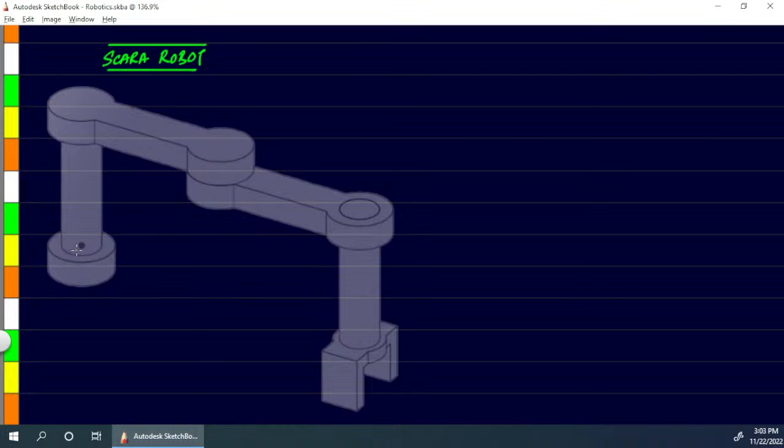We first have to identify the parts. So first step is to identify the parts. Let's call this part 0. And this whole part, the bottom and the top, both move together as a single object, so this total link is called link number 1. This link is called link number 2. This link is link number 3, and finally this last link is able to rotate about this axis, so this is called link 4. This is the gripper, you can say.